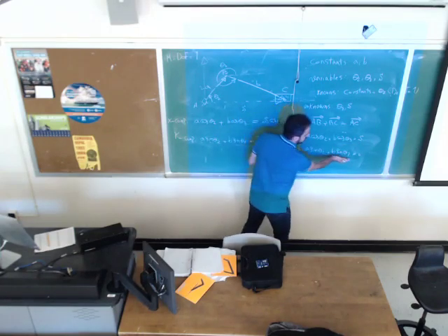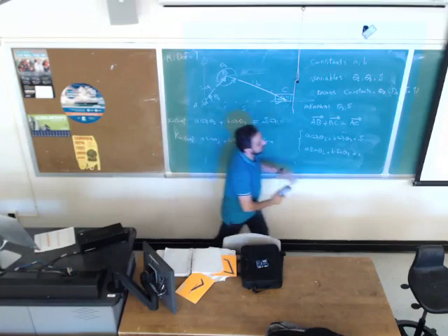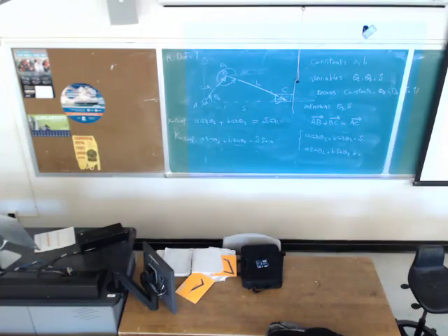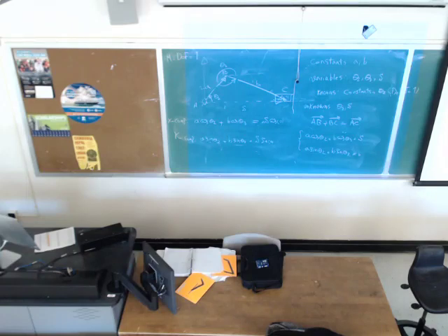It's not the right approach because when you solve for sine of theta 3, suppose sine of theta 3 is 0.5, which one is going to be my correct angle? You don't know, it's 30 or 150.